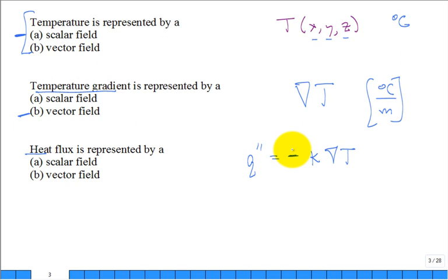The temperature gradient, you multiply by a negative sign to get the direction of the heat flux. A lot of times, maybe you'll see this in a textbook, maybe I'll do that too, they'll put a little vector symbol on top of that gradient and a little vector symbol on top of that q to emphasize that we're talking vector quantities now. All right. Hey, what are the SI units for the heat flux?